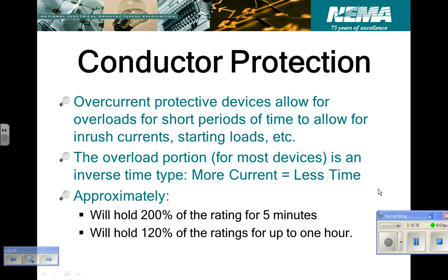They're not exact. They're not precise. Just like your timers. Why do we do trial and error testing on timers? Because none of them are exactly the same, even though they're the exact same type, like pneumatic time delay. A pneumatic time delay might be set at 5 minutes and time out at 5 minutes and a second. Some will time out 10 seconds less than 5 minutes. You've got to do trial and error. Well, the same thing is true of breakers and fuses. They're going to be a little bit different every time.